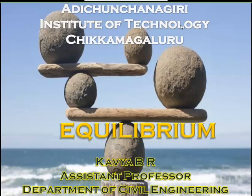This theorem is applicable only where there are three forces. If the forces are more than three, we have to use equations of equilibrium. And Lami's theorem is applicable for coplanar forces, that is forces acting on the same plane, and concurrent forces, forces acting on the same point. Now we will discuss the problems on one sphere in this video.